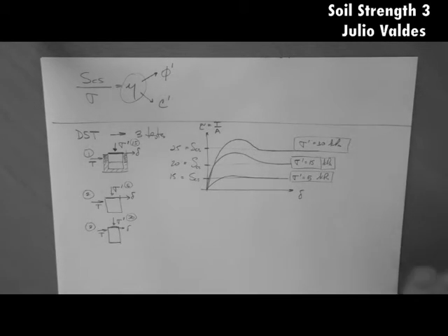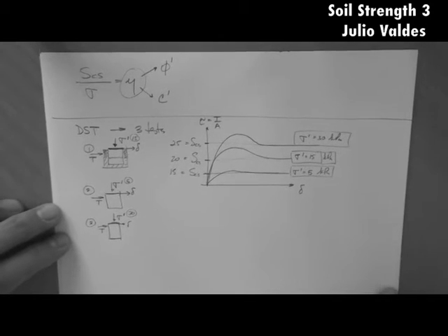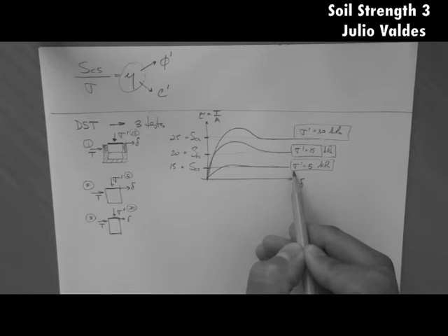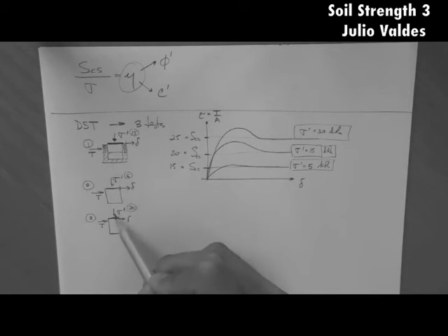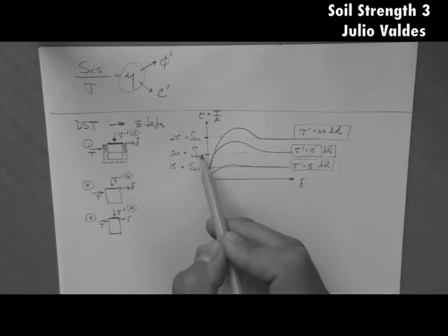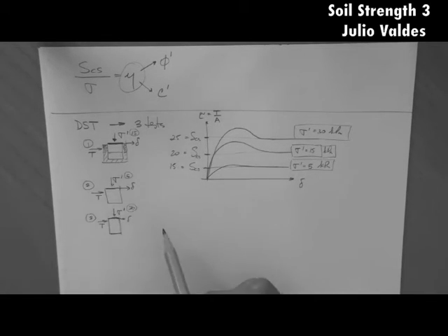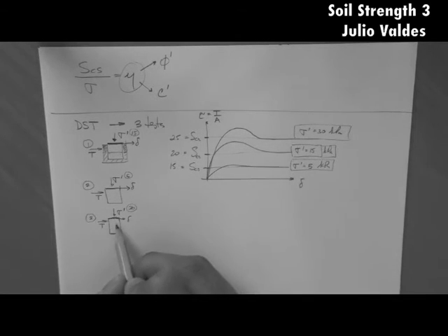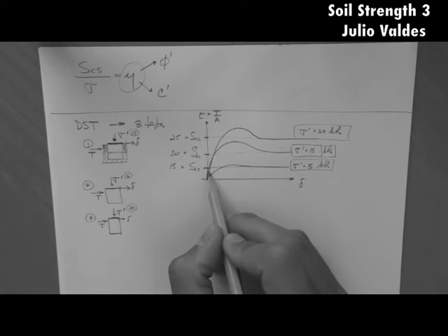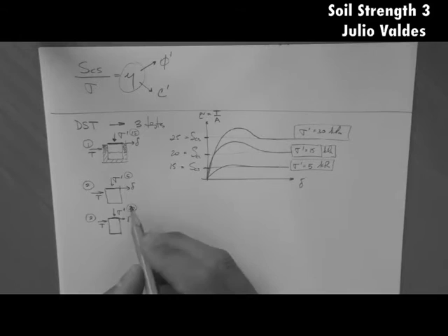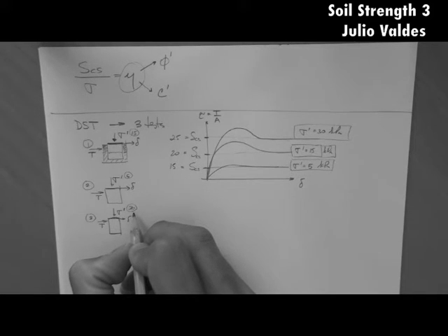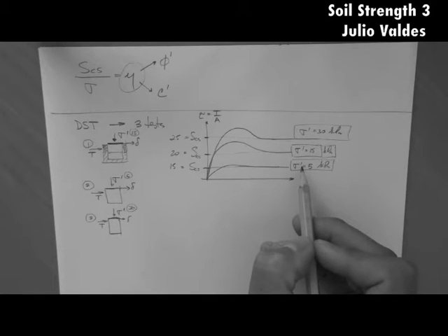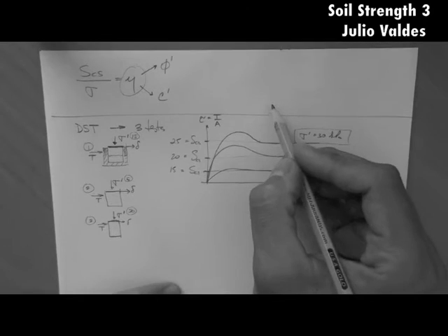Okay, now you may ask, well, why is it that we put the same soil in the three tests, how come they have different strengths if they are the same exact soil? Well, of course you know that the difference is because this soil down here, the results for which are plotted here, right? The soil down here is loaded with 30 kPa before shearing, whereas this one is loaded with 5 kPa before shearing. So, let's put a little note up here.